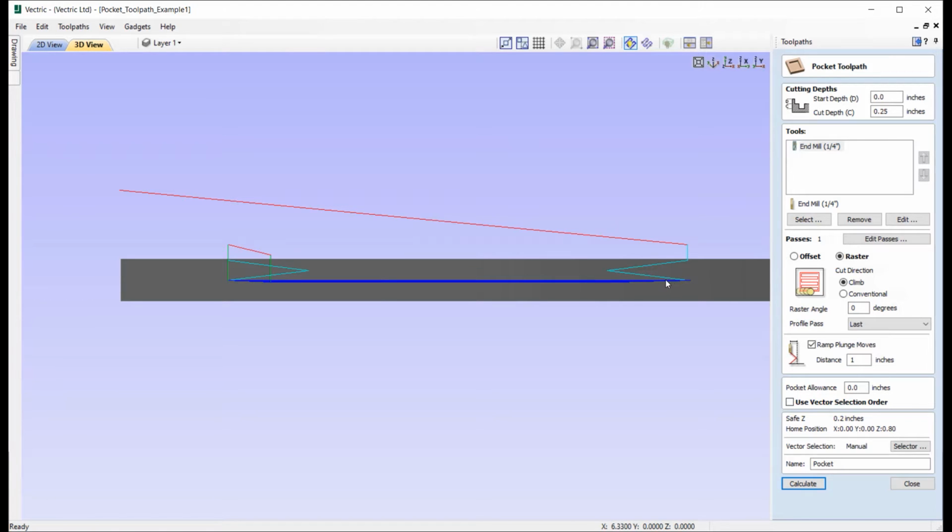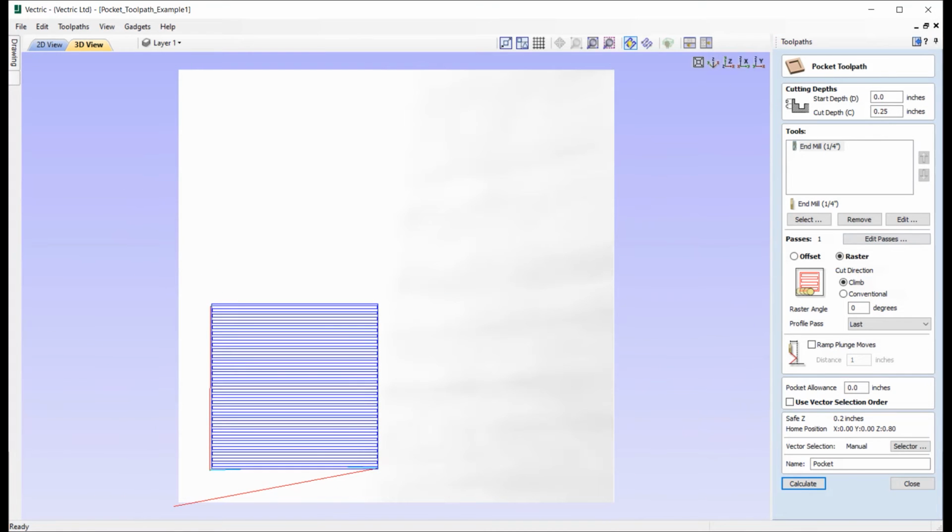And so this just basically stops you cutting vertically in with the tools. Some tools don't really have a good cutting face when moving vertically downwards, and so adding the actual ramp itself provides some horizontal movement, which just lessens the wear and tear of the tool. So let's just uncheck that option and we'll put that back in Z.